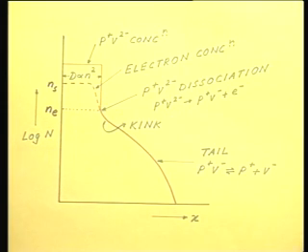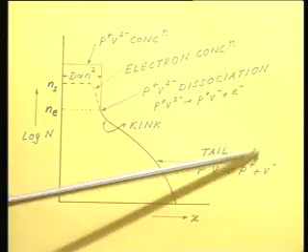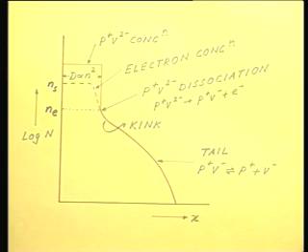Therefore, here the diffusion coefficient is dominated by a term proportional to n, and then as we further move into the semiconductor, this P+V- also dissociates, giving rise to a number of vacancies, and the diffusion is more, because diffusion is enhanced because of the availability of these vacancies.